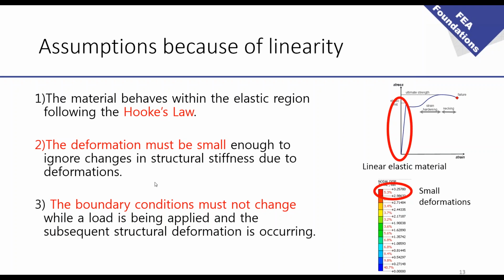This is why these assumptions allow the fact that you can consider the linearity. The third condition is that boundary conditions must not change. While a load is being applied at a certain position, your structural deformation is occurring, but you cannot say that, oh, because there is deformation, my load is changing the direction. No. In linear static, your load stays always the same direction. That's the assumption.